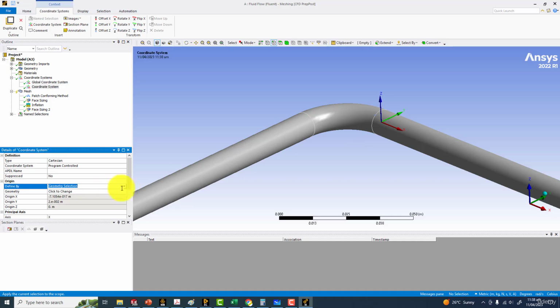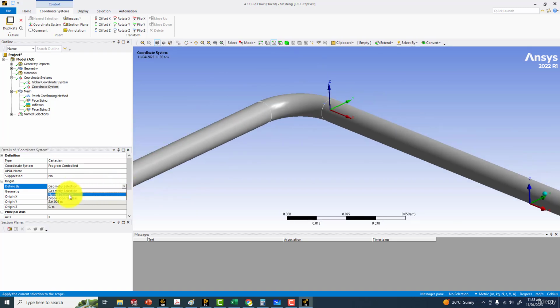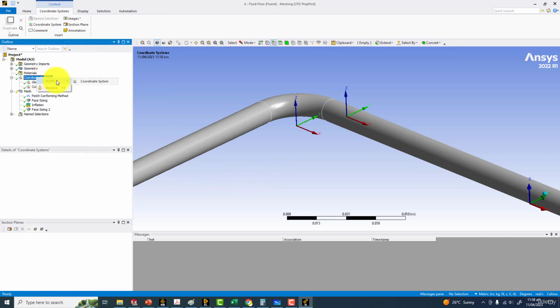And also you can choose one more thing, and this is now at the center of this location. Second thing you can do is choose the global coordinates, and from here you can provide the origin of x as 0, origin of y is 0.02, because initially it was over here, so it moved to 0.02. So let's say I move this in the x-axis by a distance of 0.01.